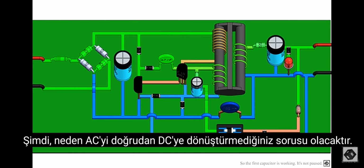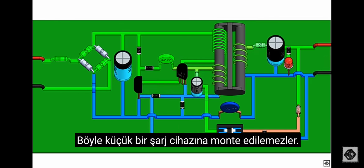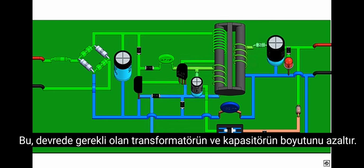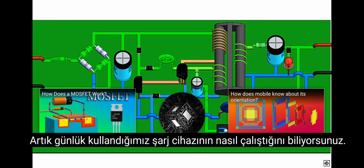Now you would have the question, why not directly convert AC to DC rather than this? This is because, for the normal power supply, which is at 50 Hz, the size of the transformer and the capacitors are large. They cannot be mounted in a small charger like this. Hence, in the charger the 50 Hz frequency is converted to 50 kHz. This reduces the size of the transformer and capacitor required in the circuit. So to change the frequency of AC, first we have to convert it to DC and then again back to AC. Now you know how the charger that we use daily works.